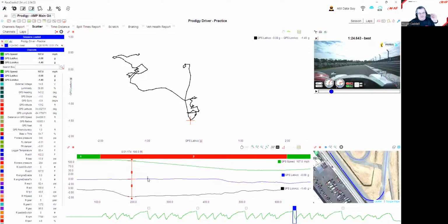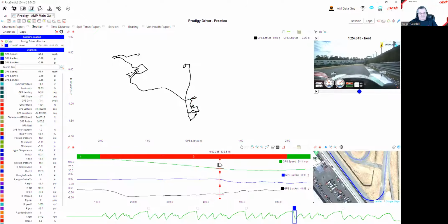And then straight line brake, it's sitting here bumping around in this area, straight line braking, and then all of a sudden, boom, the driver puts some steering into it. And you can see that he has released the braking to start to add the lateral, right? And you can see it down here. You can see that the braking is happening. The braking was maximized down here. This is the lowest of this. It's right there. And then off the brakes a little bit.